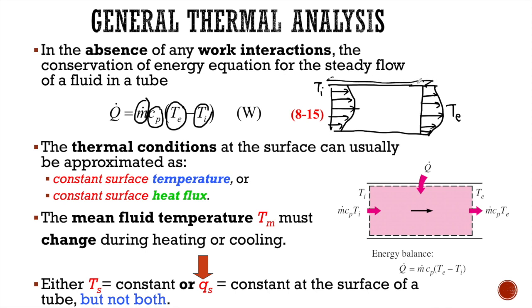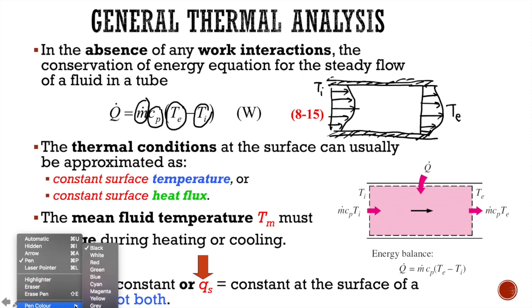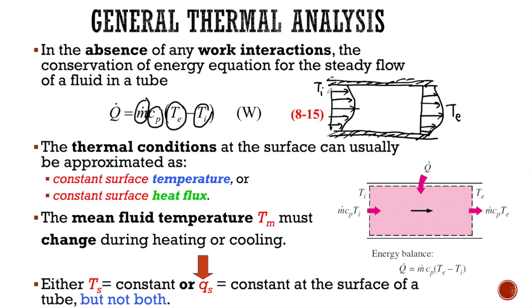So we are not calculating the fluid layers one by one. What we do is find the mean temperature of all these fluid layers. Then we only have one mean temperature for this flow. If we calculate the mean temperature, we get one temperature, which is Ti, and for the exit we get another temperature, which is T exit. So T inlet and T exit are the mean temperatures at inlet and exit.